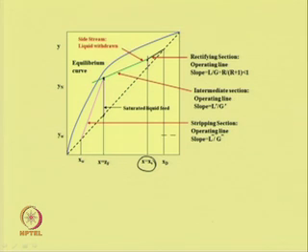The determination of the minimum reflux ratio for this type of column is a bit tricky, because the pinch point may occur at the intersection of the feed line or the side line and the equilibrium line. If the equilibrium curve has any unusual curvature, a pinch point may be found by drawing an operating line that touches the equilibrium curve.